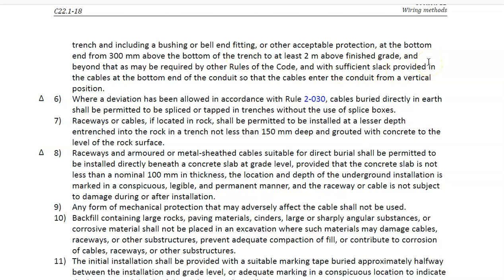So if we are going to bring a TECK cable that we're running above the earth, what we need to do is take a chunk of rigid conduit. It's supposed to have a bell end on the bottom. That's going to be the female end of the conduit. You're supposed to push your cable in through that. They want that flared end on there, so you're not going to scrape the outside conductor. You bring that thing up and through, and that's going to provide you with that protection.